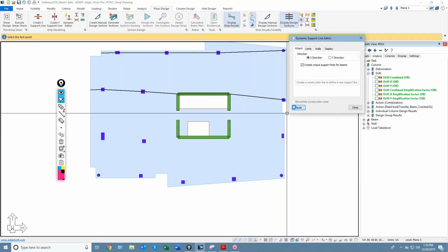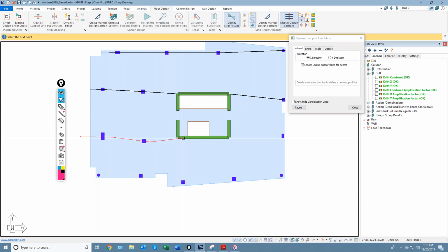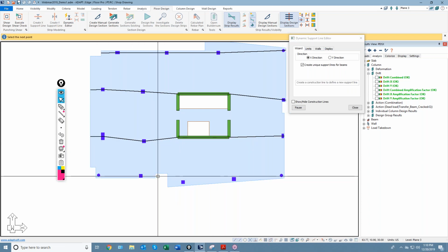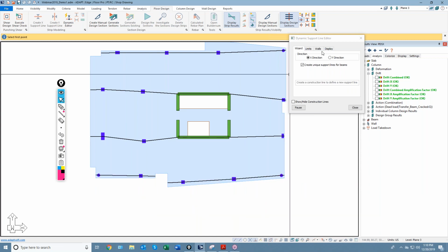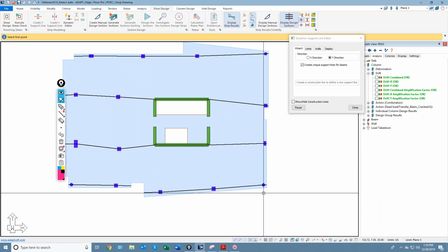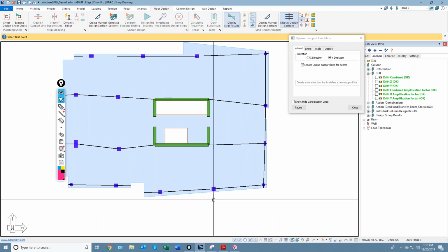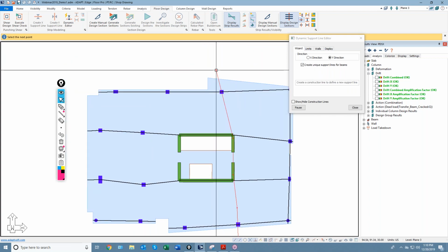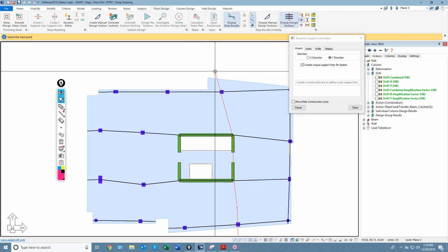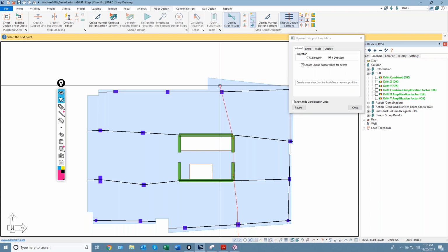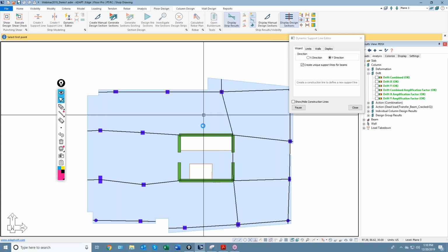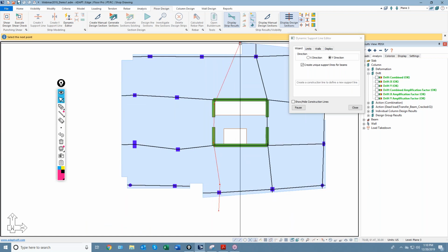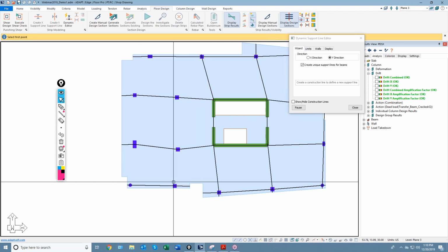Go back here, and I'll draw that one back how we would recommend, which would be, again, something like this. Okay, and then we can finish this off in this direction. There's the next two, I'll switch over to the Y direction, and I could do this on one full path. If everything gets cut, it will pick up those as supports. If I don't want this support line to exit the slab at this angle, then what I can do is just click here and then vertically up like so, and that will realign it perpendicular to the edge, or I guess in the orthogonal direction in this case.